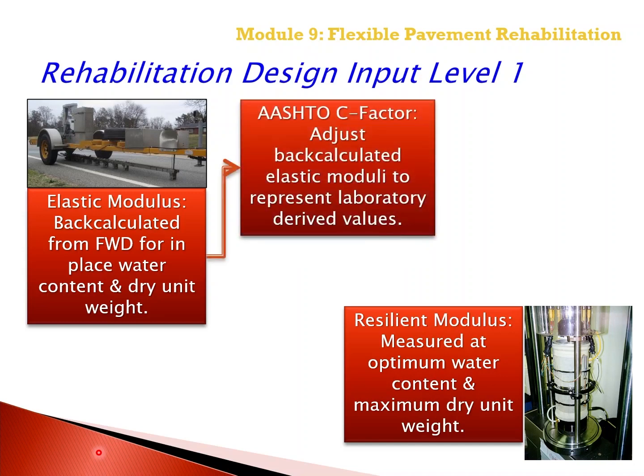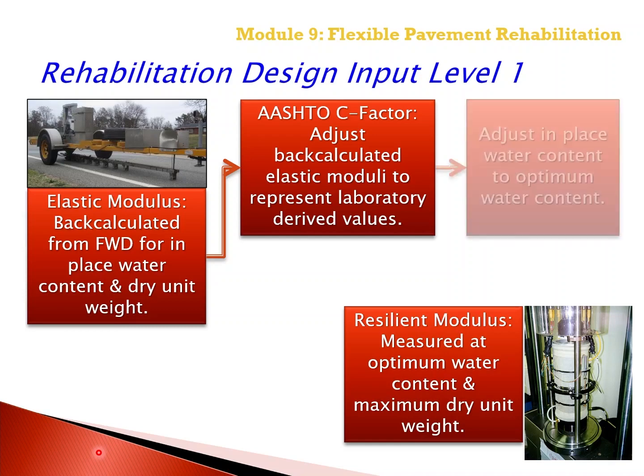We're then going to apply the AASHTO C factor to adjust the back calculated elastic modulus of the unbound layers to represent the laboratory derived values.